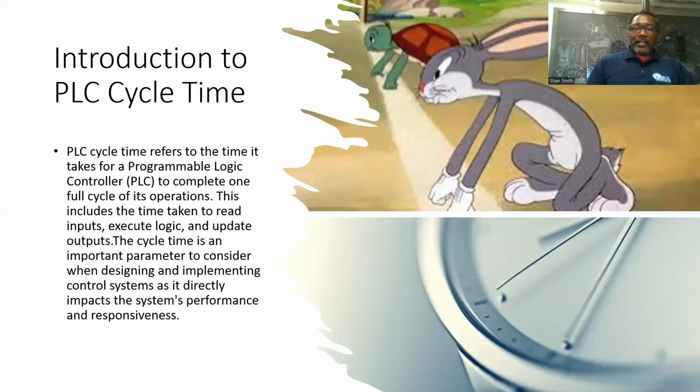PLC cycle time refers to the time it takes for a program to complete its full cycle of operations, which include reading inputs, executing logic, and updating outputs. An important parameter to consider is how many I/O you're going to have. Your cycle time is directly affected by program size. When you look at how you design your program, you can be the tortoise or the hare.